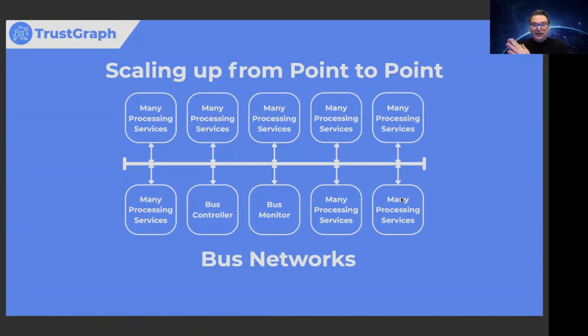And for all of those out here, all of our Pulsar fans, you're probably thinking, well, that's okay, I get where you're going now. Well, this is the old way of doing things. Well, it's not so old. It's still done that way. If you look at vehicles, the CAN bus is very similar to this. As a matter of fact, CAN is very similar to MIL-STD-1553, which again, I was working with on an aircraft like the C-130J, and so many aircraft and so many applications still use that bus network today.